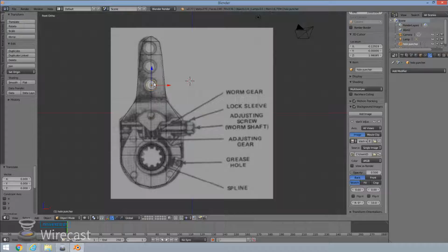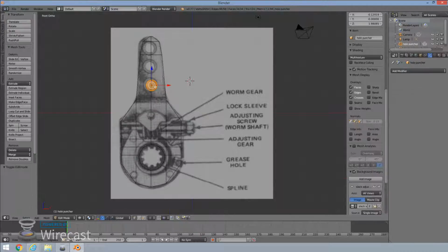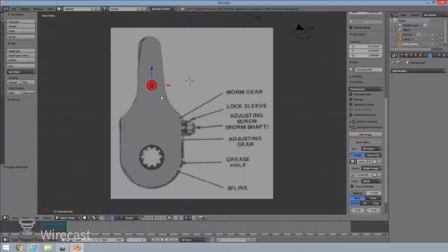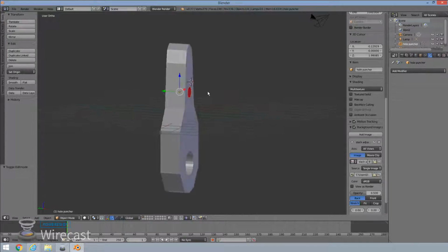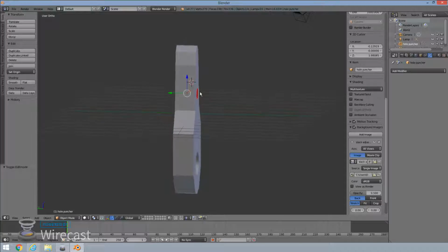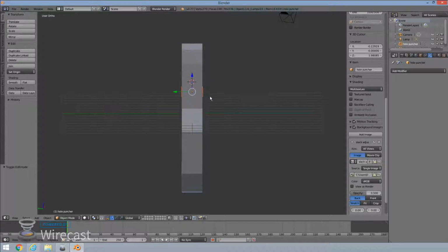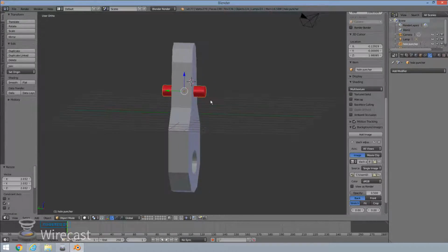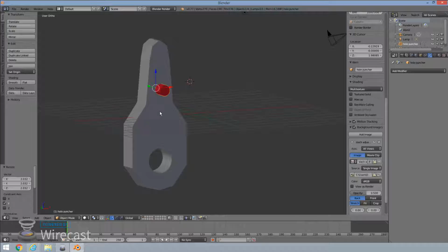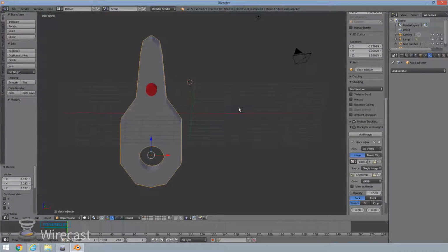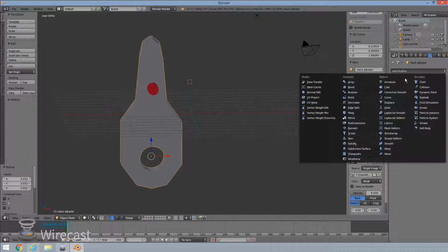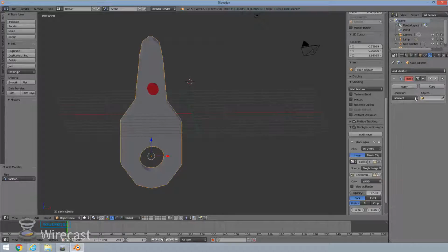Okay, so wireframe, I got it roughly in there. Go out of wireframe, so hit Z again. I'm going to make sure my tool, my hole puncher, goes all the way through, which it does, but I'm going to just play it safe and scale it on the y-axis, S, Y. Make sure it's all the way through, which it is. Go back to the object needing to be modified. Go into my modifiers panel here, select the drop down box, hit Boolean, and just do it all over again. Difference, find my tool, apply, done.